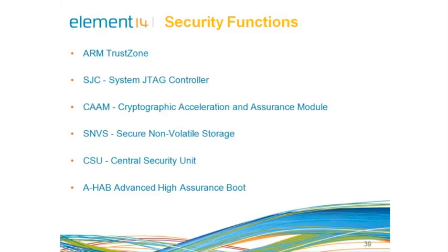It has CSU, that is Central Security Unit, which is enhanced for the IC Identification Module, that is IIM, and will be configured during boot by eFUSEs and will determine the security level operation modes as well as the TZ, that is TrustZone policy. It has AHAB, that is Advanced High Assurance Boot, version 4, with new embedded enhancements such as SHA-256. It can use a 2048-bit RSA key, and version control mechanisms. It has warm boot. It has CSU and TZ initializations.